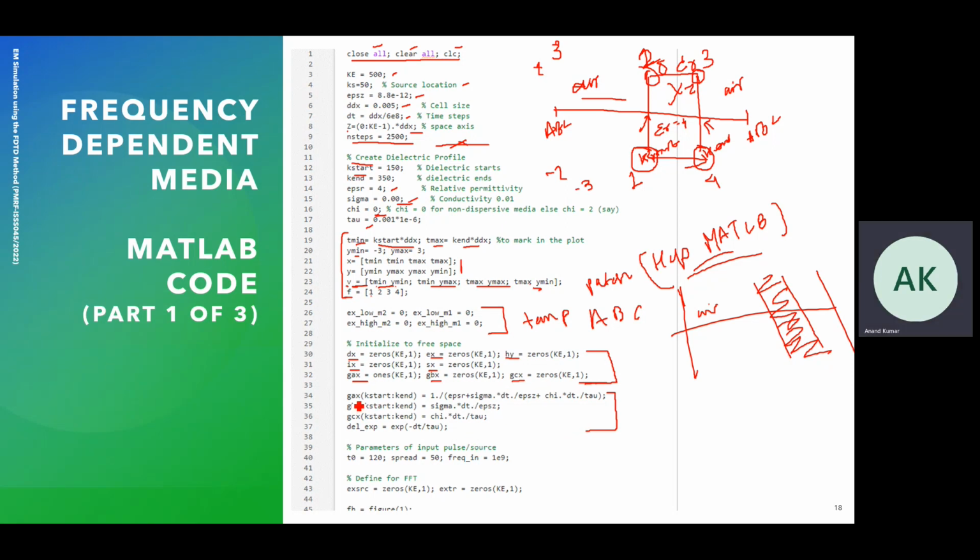For that, we define gx from k start to k end. This boundary is k start and this boundary is k end, and within this we define the epsilon, sigma, epsilon z, chi, all these variables. Similarly, we define gbx and gcx between k start and k end, and we modify the coefficients within this. Once they are modified, they will implicitly update Maxwell's equation within this region differently as compared to air.